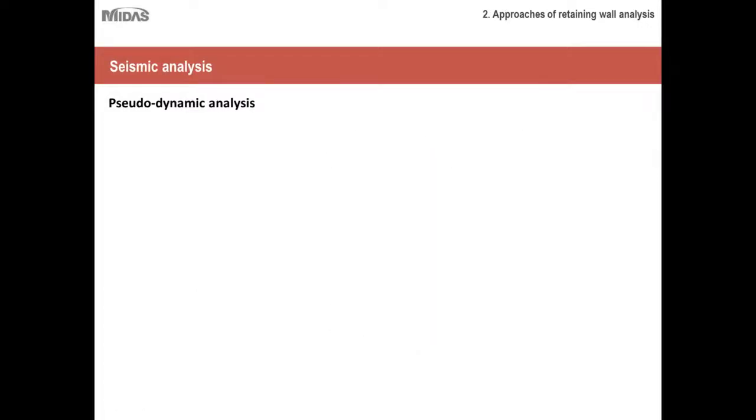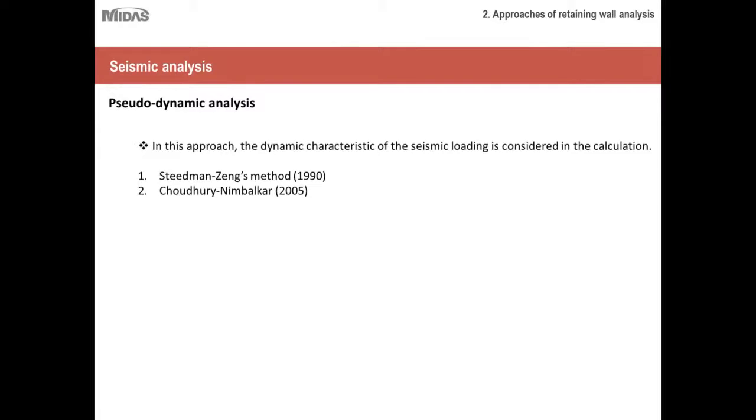And now let's talk about pseudo-dynamic analysis. This approach considers the dynamic characteristic of the seismic loading, and if you would like to read more, you can read Steedman and Zeng's method or Choudhury and Nimbalkar's method. Like I mentioned before, this method is hardly used, and to be honest with you, I have not seen engineers using pseudo-dynamic analysis at all.